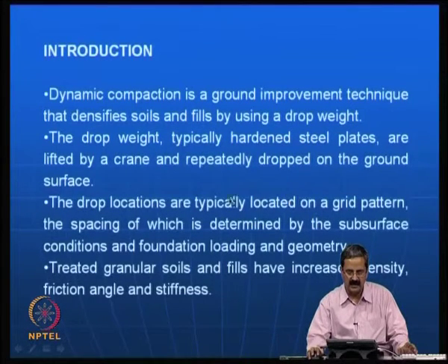The drop locations are typically on a grid pattern, as we will see in a design in a few minutes, the spacing of which is determined by the subsurface conditions, foundation loading and geometry. Essentially, most of the time we have a grid pattern, and the main things are the subsoil conditions, to what extent the soil needs to be improved, what foundation loading is coming, and the geometry. All that is very important.